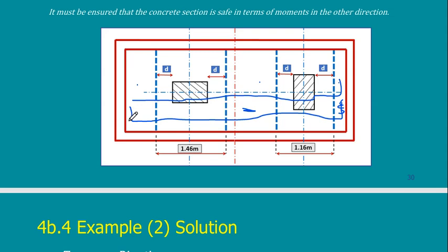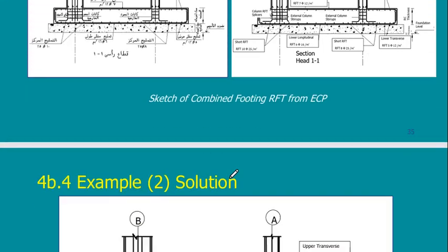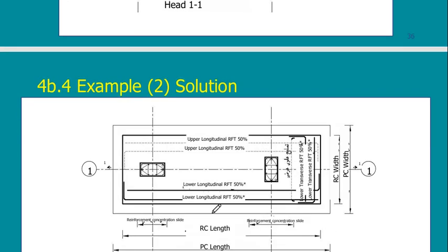So one with a leg here and one with a leg in the other direction. Instead of using all of my amount of steel as a U bar, I'm going to use it as an L bar, 50% of the L bar and 50% of the same L bar, but in the opposite direction for the leg. This is what we do in case we have a very high amount of steel. One will be like this and the one next to it will be like this. This is just for cost saving. Suppose you don't do this, it's okay, but you are not saving for your client or for the owner.